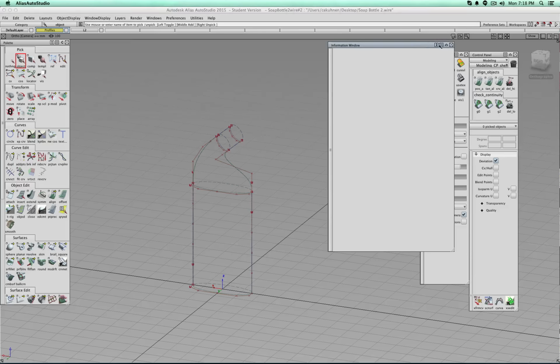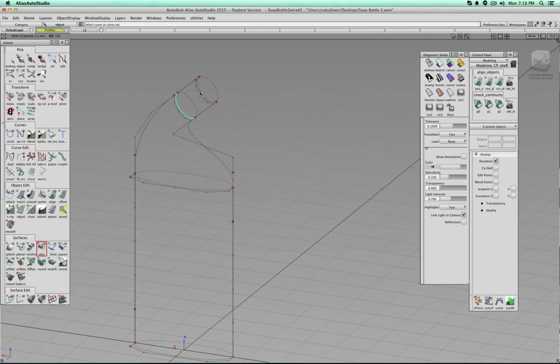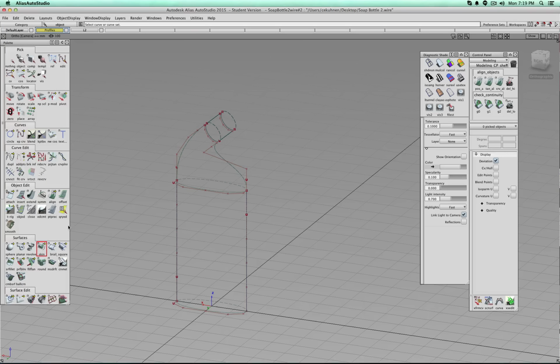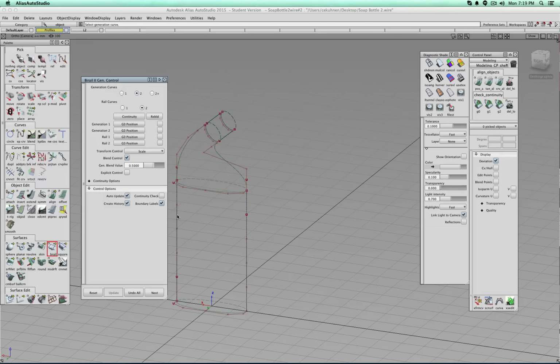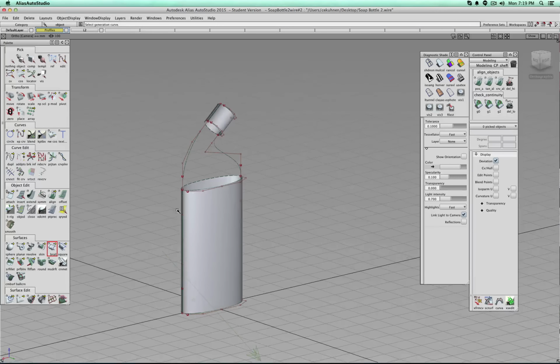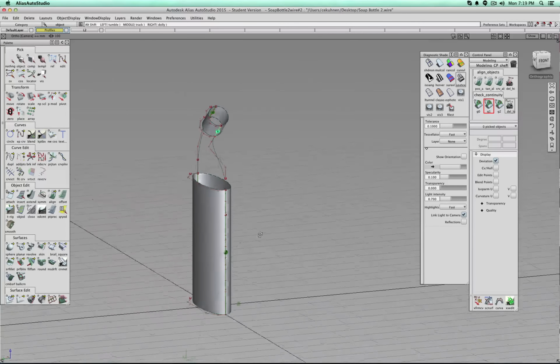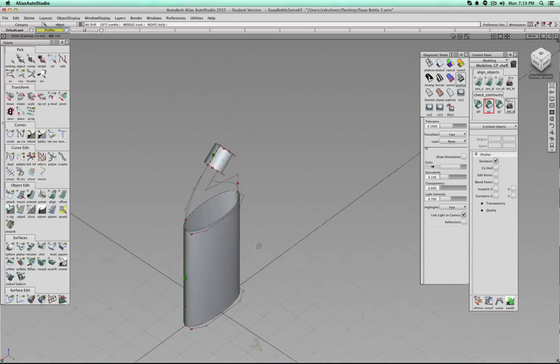Okay, so this is kind of like my curve layout. Let's quickly take a look at some surfacing options. So I can go to skin and say hue to hue. Okay, and for example here I use this one, a rail surface, check continuity. Of course I can't really check anything because there's no surface attached, but now for example I can click here under check continuity, G1. So I want to make sure that, for example, along those edges the surfaces are tangent to the mirror plane, and as you see they all are.